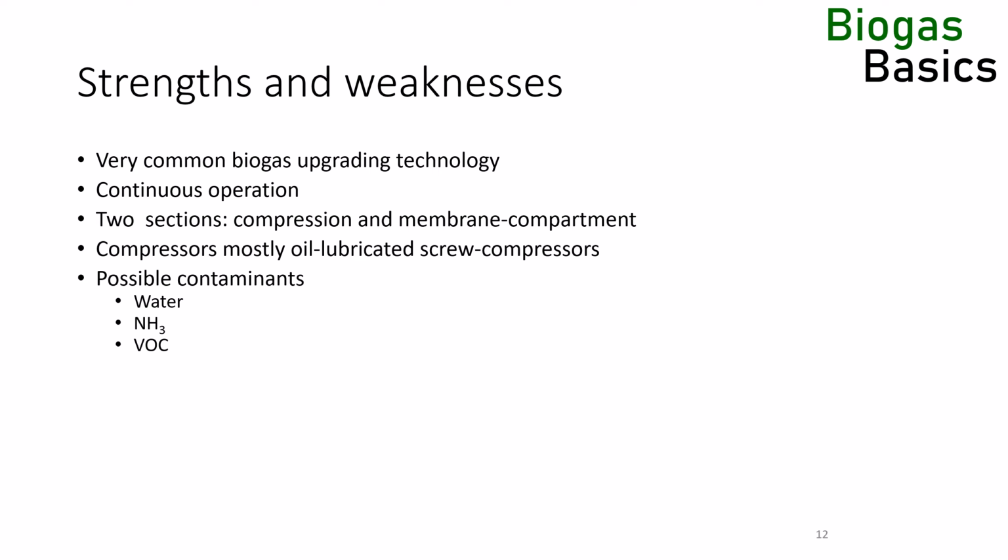They create an additional layer on the membrane fiber, creating a thicker layer for the CO2 to diffuse through. Relevant VOCs can be roughly split into 3 groups. Small molecules like acetone, methyl ethyl ketone, butanol are created in fermentation reactions, often at lower pH and high temperatures, for example in hydrolysis tanks. Terpenes like limonene and pinene are created in food and green waste fermentation.